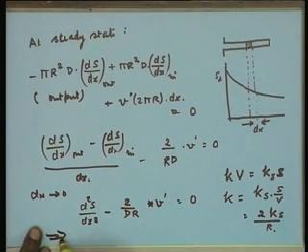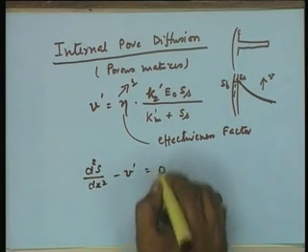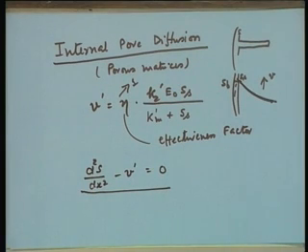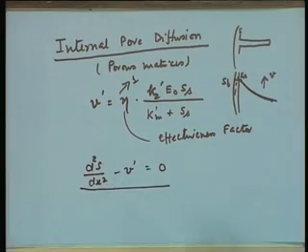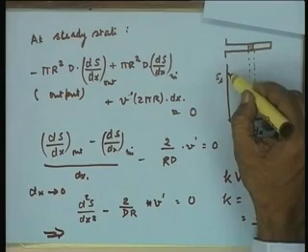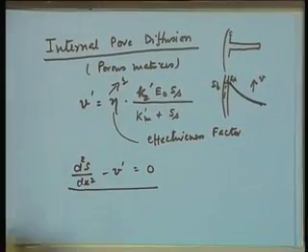So therefore one can write here d2S over dx square minus k dash equal to 0 as the basic second order differential equation. If you substitute the reaction rate term depending on the nature of the reaction, either by assuming first order kinetics or zero order kinetics or even Michaelis-Menten kinetics, you can get a solution. Of course Michaelis-Menten kinetics will require a numerical solution, as an analytical solution may be difficult. You can get the substrate concentration as a function of the distance x from the surface. Basically, a solution of this will give you the substrate concentration profile in the pore, or inside the particle.